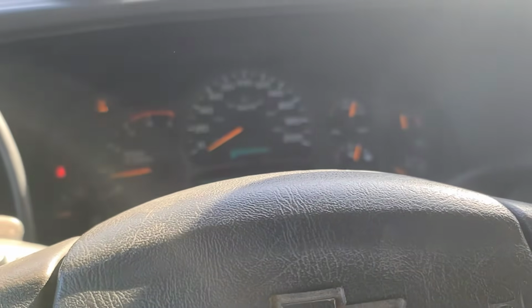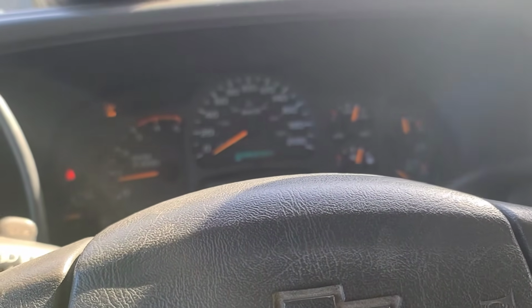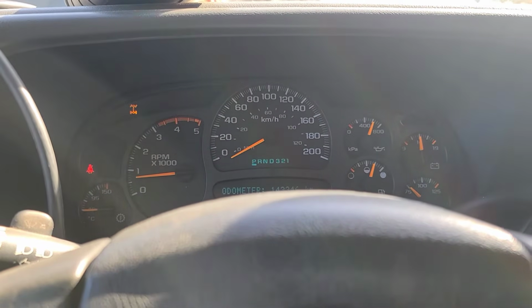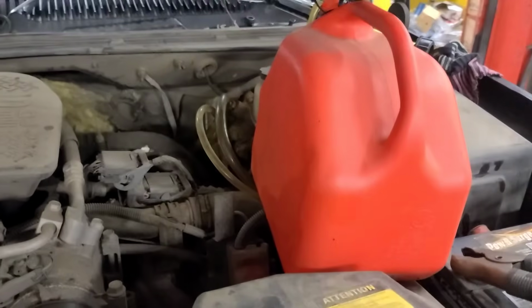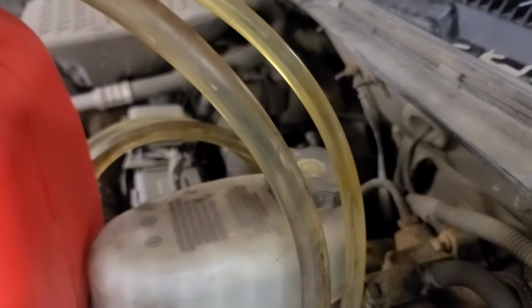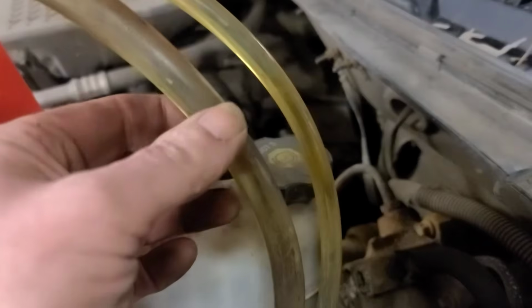We've got a suction leak into the fuel system, so I'm going to gingerly drive this in the shop now where I can work on it more conveniently. The suction line is 1/2 inch, the return line is 3/8. All I did was push them on.